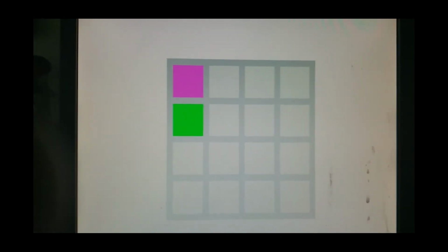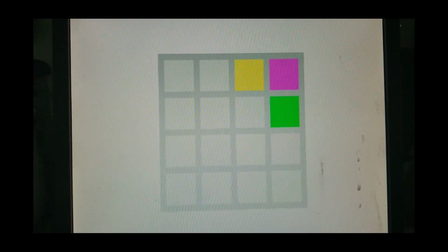As we explained earlier, this is really due to bugs with the clock signal, the data not coming in on time if we use blocking versus non-blocking assignments. One of our theories is that it has to do with how big our multi-dimensional array is for the board, because it's a 4x4 array with 16-byte words in each cell. That's a lot of information to be passing between cycles, and we think that's where we're getting an issue. But the user can keep on playing, and blocks will appear.